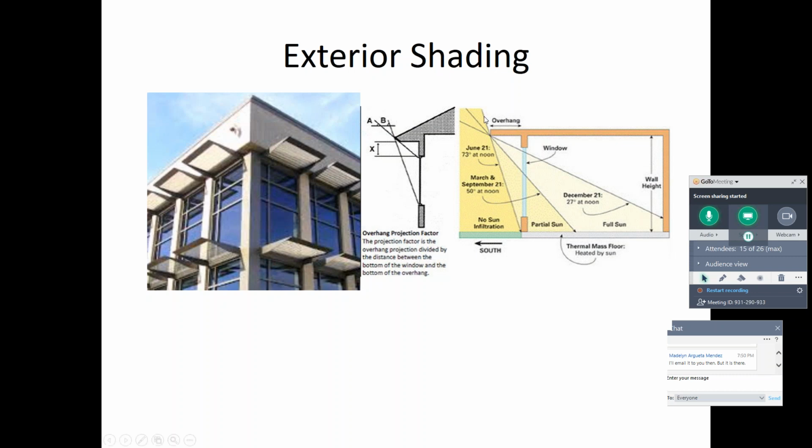But it does really control light in a special way. And here we just show how that might be on a site. So it's different times controlling it, and sometimes it's allowing it into the space or out, but it's always protecting us from the elements. And then depending on which side of the building, if you get too much direct sunlight at a certain angle, you could add an overhang but have a normal window with no coating, right? So you might combine elements such as an overhang and a window to do what you want to do.